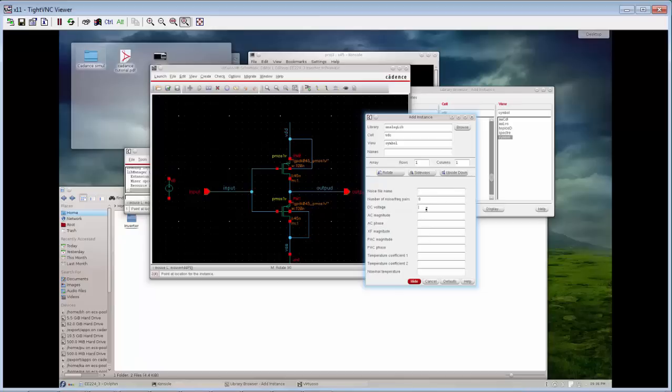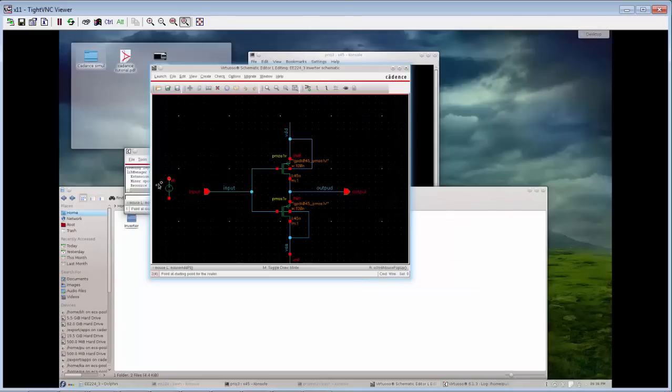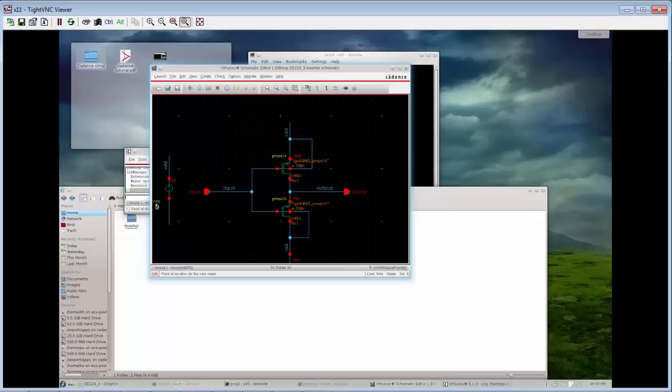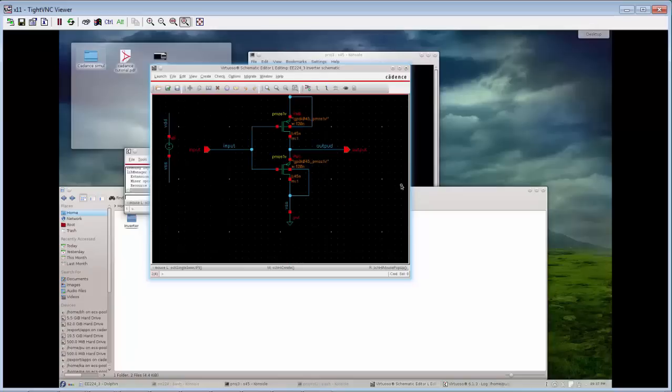What's the value? If your value is 1 volt, then click hide. Let's wire up. We don't need to attach all the way till that point. Just need to name it the same way, the same name, and they are by default connected. It is VDD right now here. So once we name this wire as VDD and this as ground, that will be automatically connected. Just name it VDD, VSS, hide VDD, then the VSS, and also let's put a common ground.